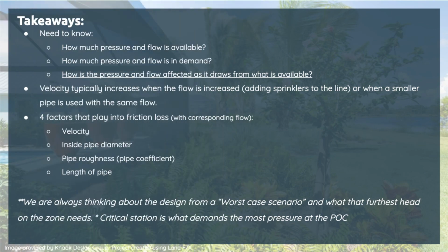Yeah, no, that's a pretty simple one. I mean, when we talked about it, it is what it is from a design perspective. That's the equipment you picked. That is the specifications that they hold, and those charts are tricky, but required inlet is always typically higher than the required outlet based on flows. So if your flow is on the high end of that chart, it's going to be creating a lot of losses based on what you have to have on that inlet side.